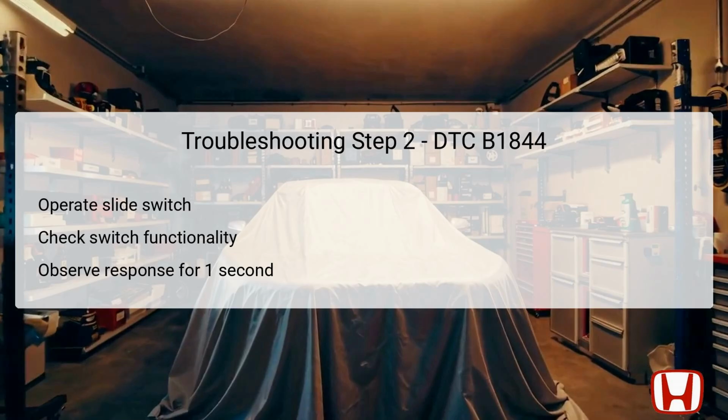If the switch fails to initiate movement, it signals that there may be an issue with either the switch itself or the connected systems. Continuous observance of the seat's response during this operation is crucial to determine the status of the circuit. Proper functionality at this stage confirms that the main control systems are operational, providing a clearer path for identifying faults if issues persist.